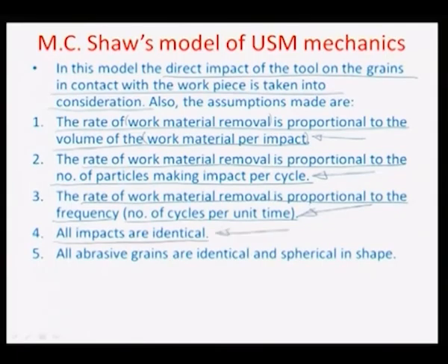and we assume that there is no non-idealized situation. So the situation that we are assuming is that there is a tool which comes close to the surface, and there are certain grains which are trapped between the tool and the workpiece, and when the tool moves apart, there is always cavitation or erosion of the material which has been brittle fractured, and the next set of abrasive grains comes when the tool again approaches.